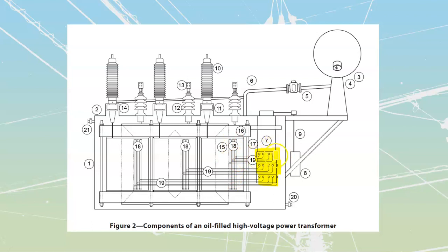This is going to be a rotary set of brushes that are going to make and break these, sometimes with small reactors that are attached to it, and then that rotary set of brushes is taken outside, coupled through mechanical shafts down to a motor that is then going to be used to change these taps. We don't obviously want to send linesmen into these to change the taps. First of all, changing taps is a bit dangerous because there is always potential for failure. And secondly, we want to be able to do this remotely from wherever we've got our control yard for these.